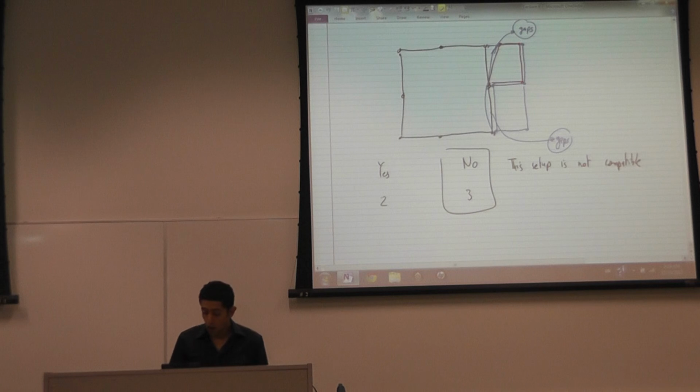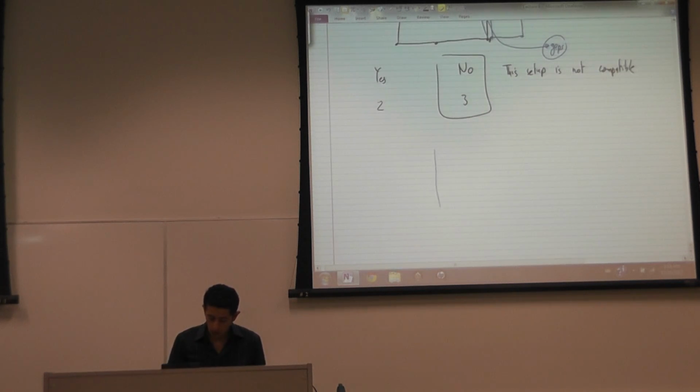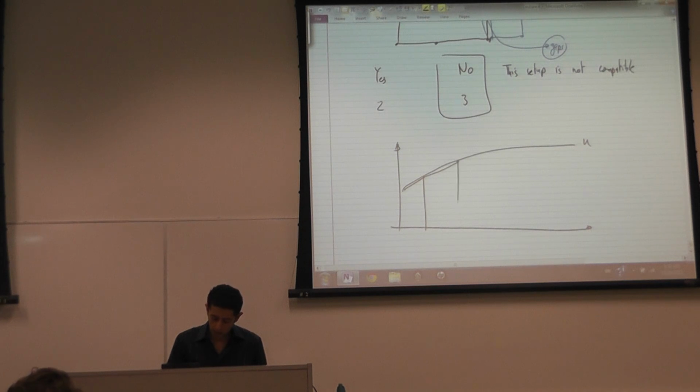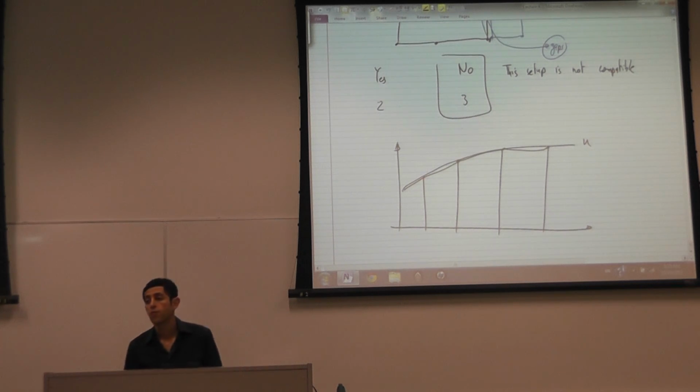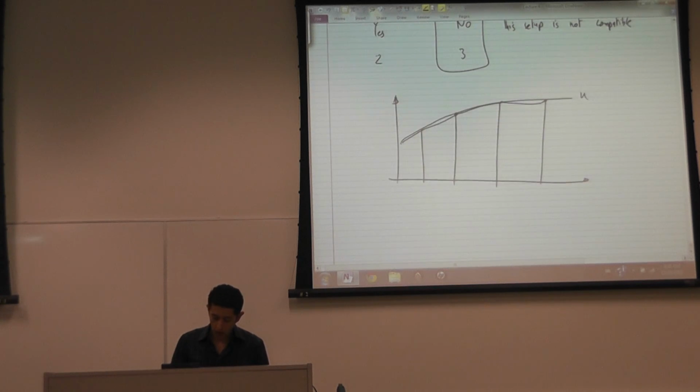So basically, incompatibility is almost like saying the following. We're using C0. What does C0 mean? It means this is the displacement. I'm using compatible elements, which means right at the interface, the displacements are the same. That's compatibility. You, perhaps, for some reason, would like to model something using an approximation that looks like this.